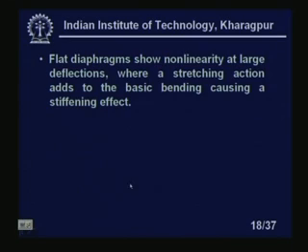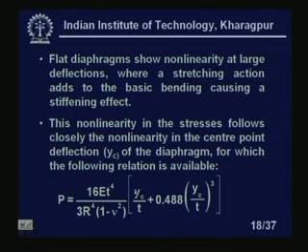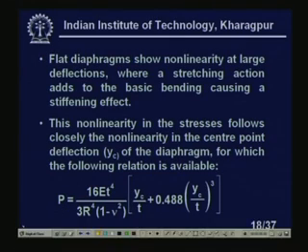A flat diaphragm shows nonlinearity at large deflections, whereas stretching action adds to the basic bending, causing a stiffening effect. So, the deflection of the central point has to be kept minimum, otherwise there will be distortions. This nonlinearity in these stresses follows closely the nonlinearity in the center point deflection YC of the diaphragm, for which the following relation is available. This is the relation between the pressure P and YC.